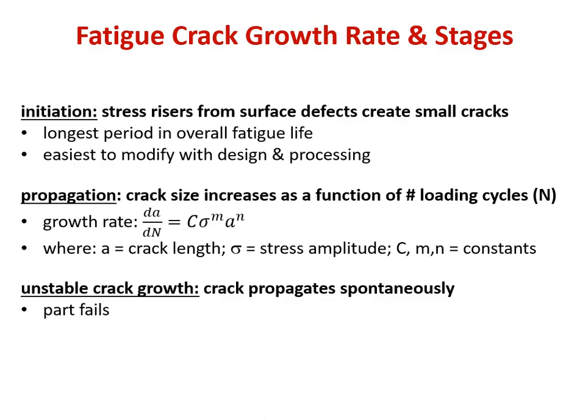Once it is present as a crack, it will encounter a period of fairly regular growth that follows a power law that you can see there in the propagation section. And then, of course, once it reaches a length for which the applied design stress exceeds, where that resultant K applied exceeds our K1C, we'll have spontaneous failure.